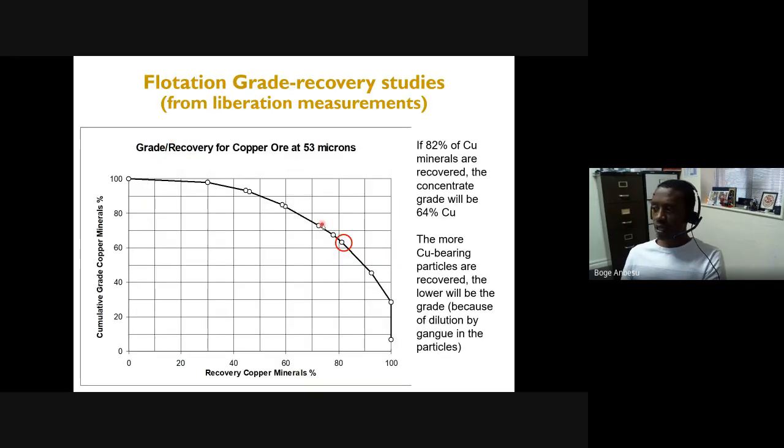So in this case, you can either push the quality of the concentrate. For example, I want a large fraction of copper in my concentrate. That's the grade of copper. If you try to push the grade, usually your recovery drops because we're trying to get a high quality copper. We're trying to reject as much of the waste. Usually when we try to reject much of the waste, some of the copper will be lost with the waste. So your recovery drops.